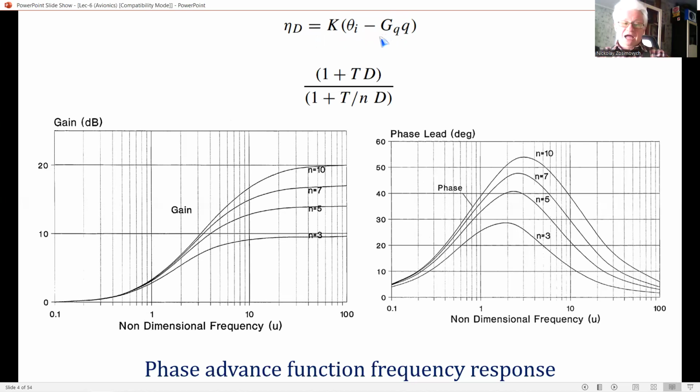In practice, additional control terms from other sensors like incidence and normal acceleration may be required. The value of K and the sensor gearings would also almost certainly need to be varied with height and air speed by an air data gain scheduling system, as already mentioned some seconds ago.